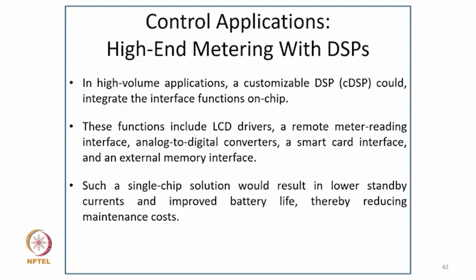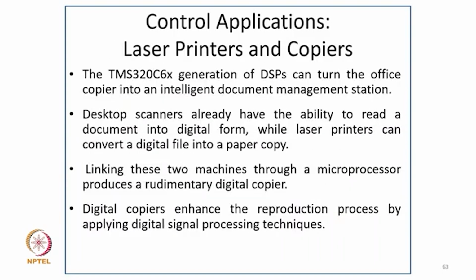So in high-volume applications, a customizable DSP, CDSP, could integrate the interface functions on-chip, and these functions include the LCD drivers, a remote meter reading interface, analog to digital converters, a smart card interface, and an external memory interface. Such a single-chip solution would result in low standby currents and improved battery life, thereby reducing maintenance cost.